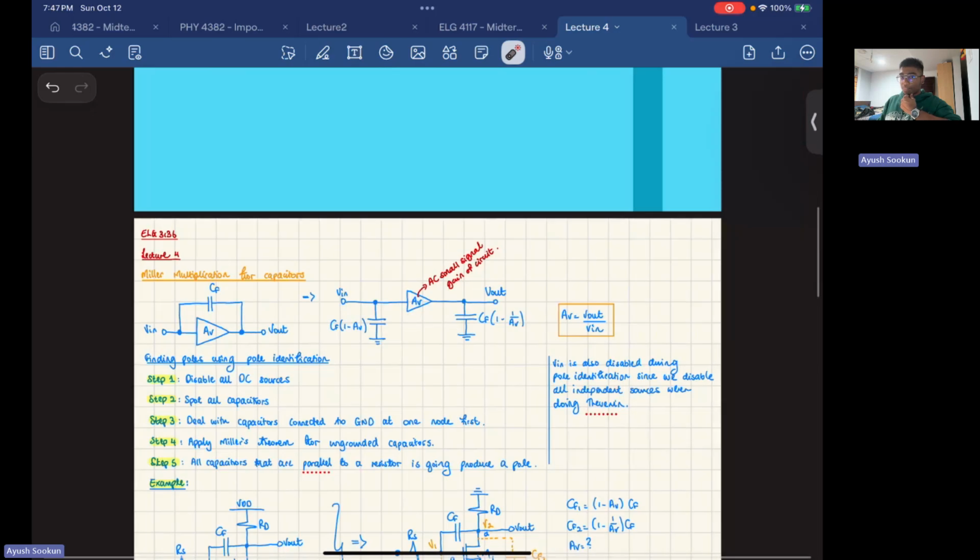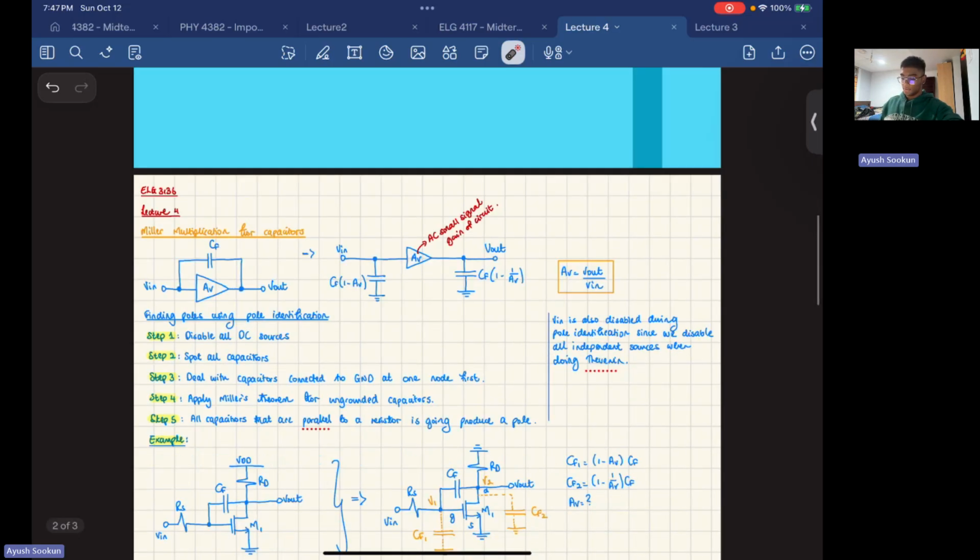And this is where I think memorizing the gain equations of the common circuits is very, very important. Common source, common drain, common emitter, common collector, common base, common gate, all of those. Memorize these gain equations, because most of the time you're going to have a capacitor connected between the input and output of such amplifiers. If you know the gain, you don't need to do any analysis. You know that without a capacitor, this is my gain equation, so I can take that and replace it for AV. Nice and simple. It saves you like 10 minutes. So do memorize that. That's a pro tip.